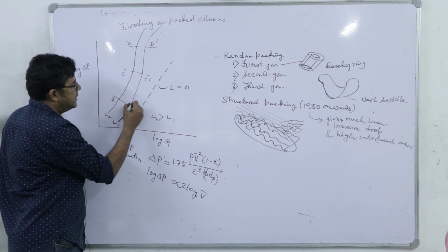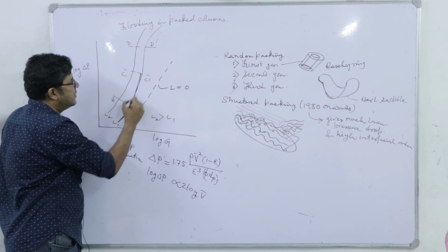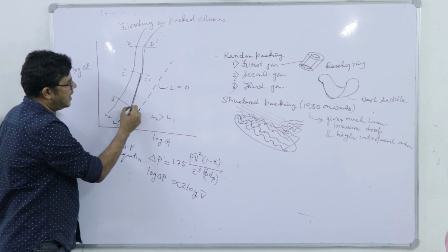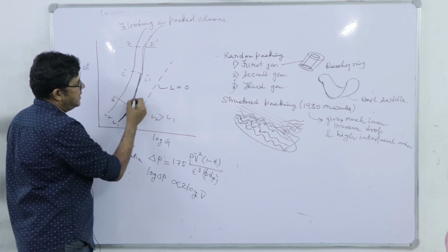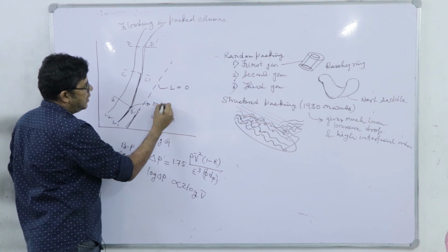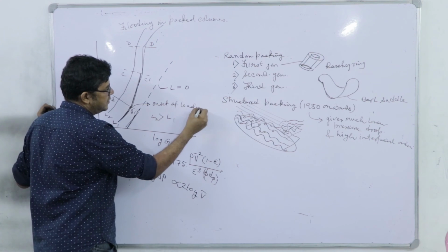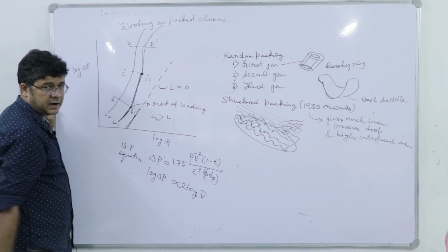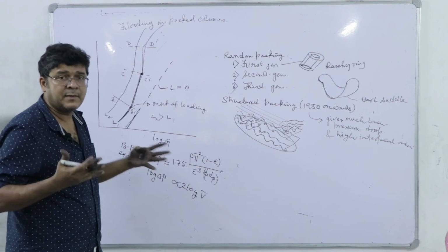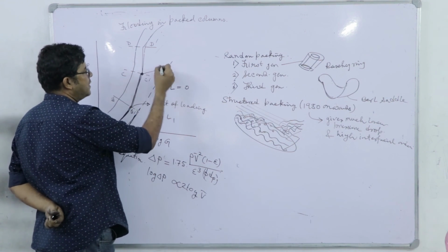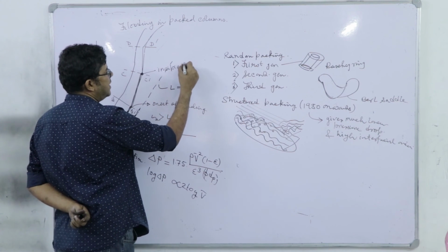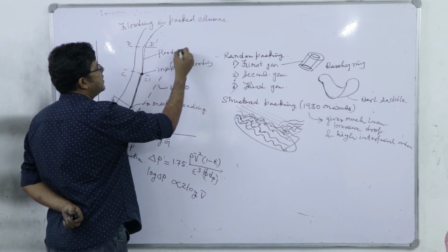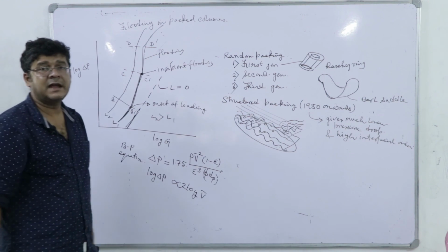After some point, the pressure drop starts increasing, further it increases and then it goes down to some extent. So, when it starts increasing, there is a discontinuity in the derivative, and that is called onset of loading, which means the liquid accumulation just has started, and this is the loading region of this curve, right. Flooding means excessive amount of liquid accumulation. This is called the onset of flooding, that is incipient flooding, right, and that is the flooding region where the liquid accumulation is huge.